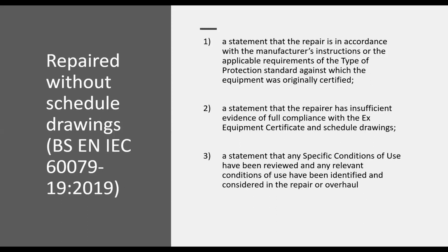A lot of the certificates now say, without the scheduled drawings, the flame paths cannot be reclaimed. If you come on an EX course by the AEMT, or if you read the standard correctly, you can do that. If you're following the repair standard, you do not need the schedule drawings, but you need to state in your paperwork the route you are going through to do this.